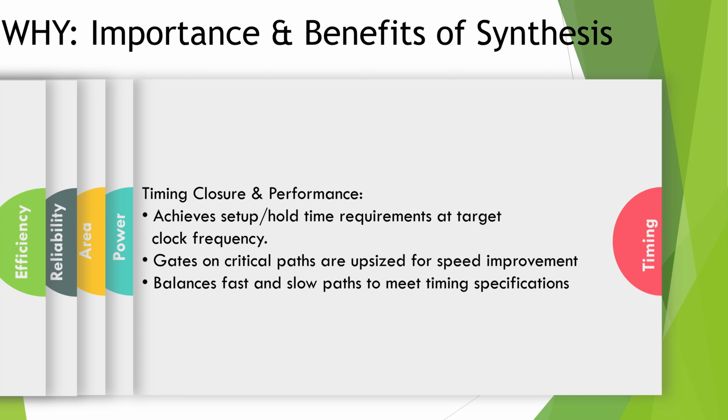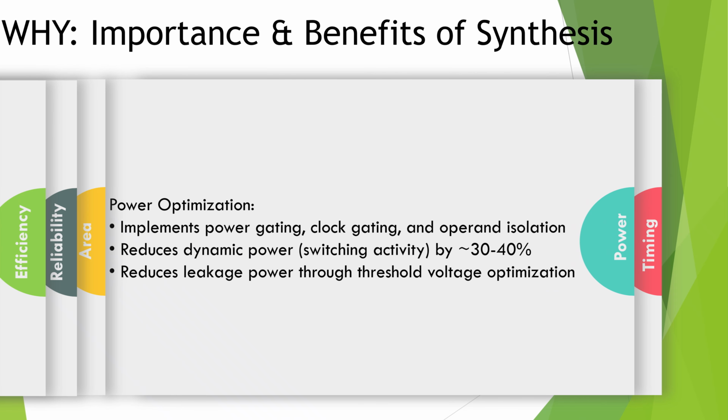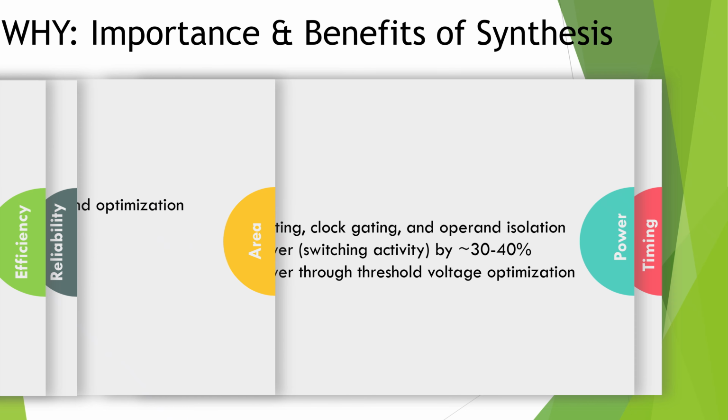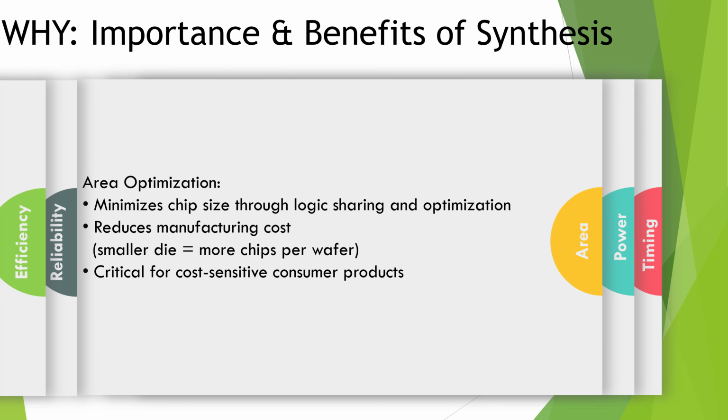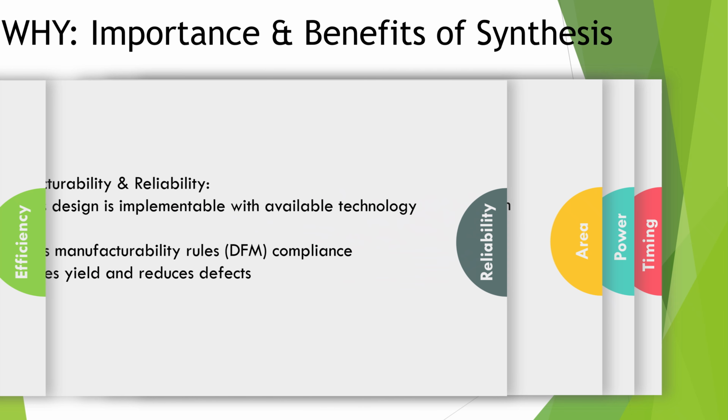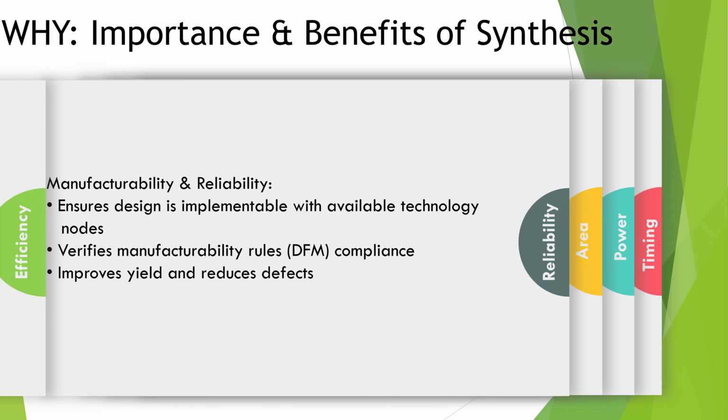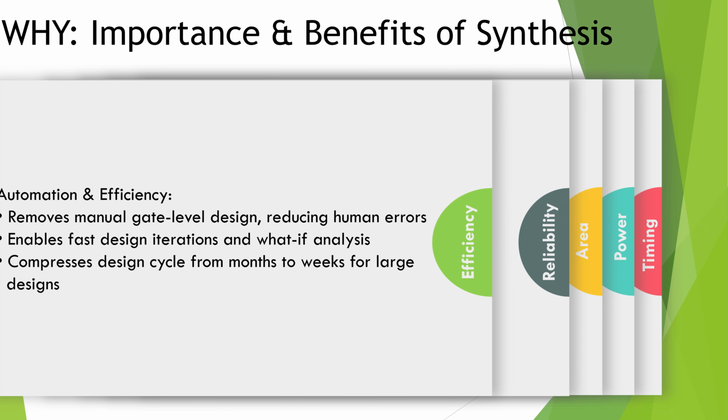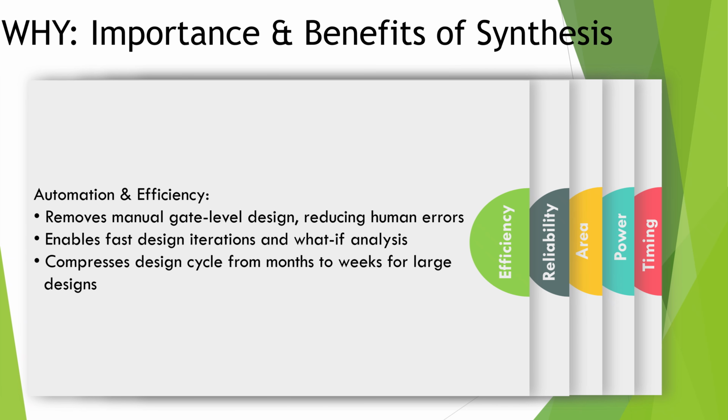Exactly. Done well, synthesis helps you close timing at your target frequency, reduce both dynamic and leakage power, and minimize area to reduce cost. It also ensures that the design is implementable in the target technology, respecting the available cells and rules. So synthesis is not just some compiler step, it's a central optimization step that decides how good or bad your design becomes in real silicon. That's exactly the mindset you should have.